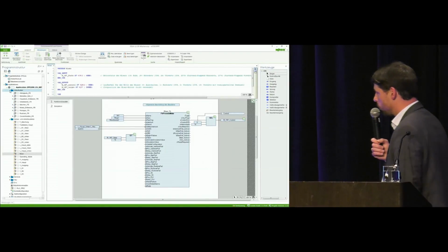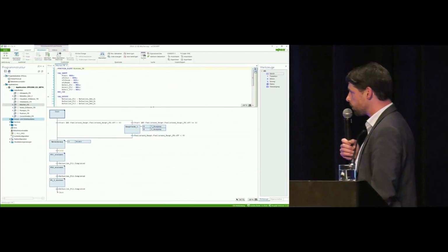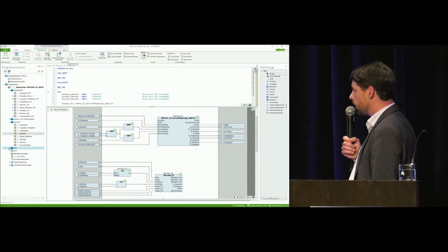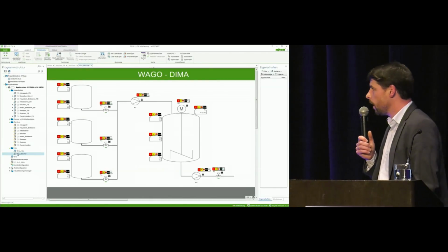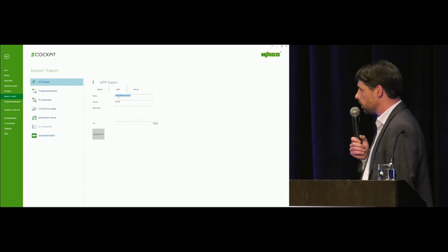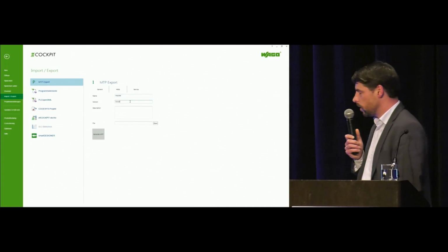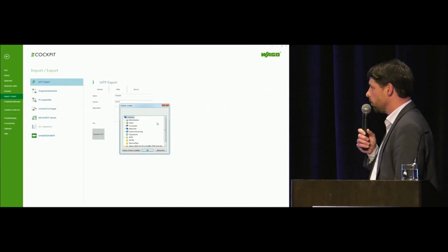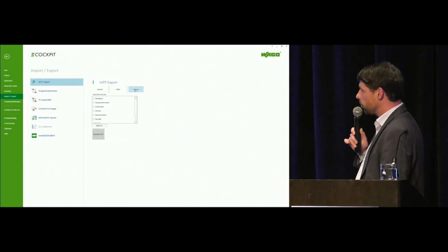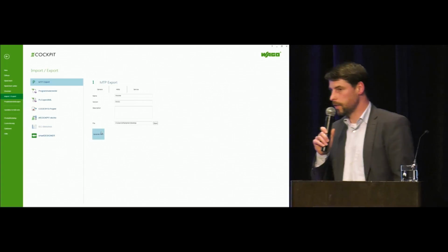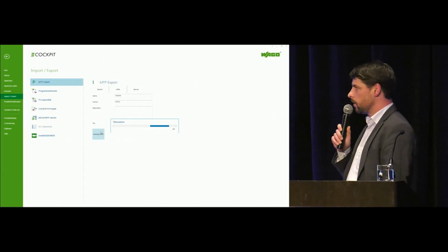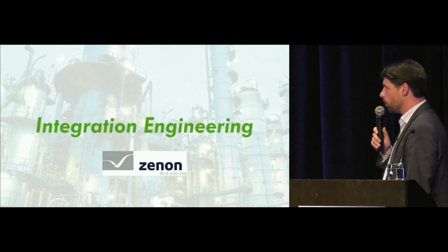This is the program code at the ready state. Everything is there. The sequences, the equipment specific function blocks. And also the HMI is in there. What I will do now is generate an MTP file out of this. This is done by an additional algorithm which is also included in the engineering software. This is the HMI I'm choosing, and these are the services which are inside the program code. At this step, the module is bound and it is saved on the local machine.